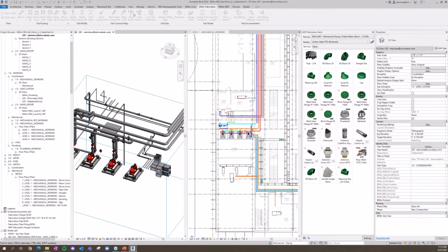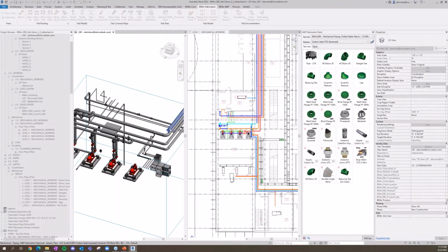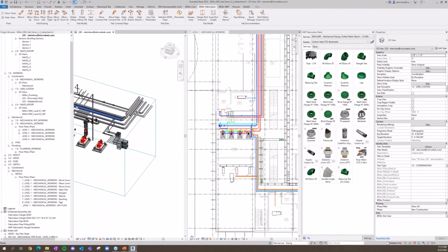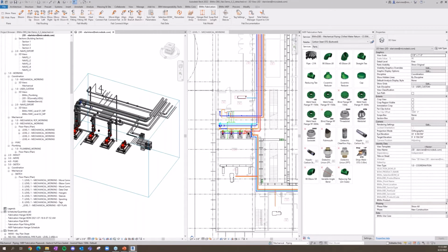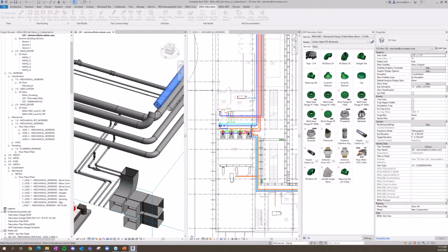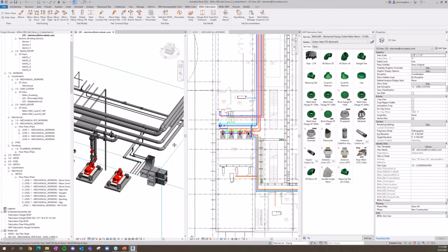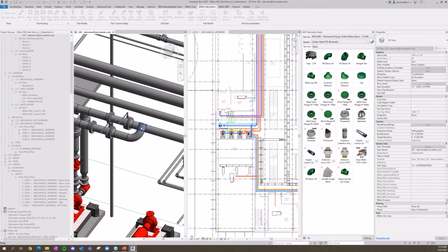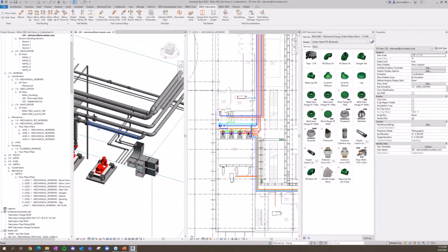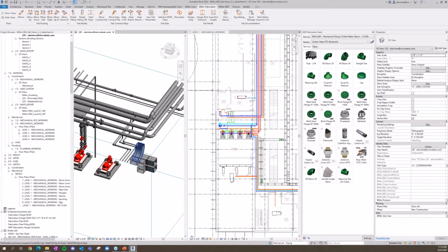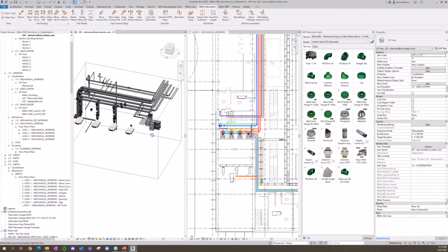Oh, and if I use align branch, we'll make sure to actually click the pipe and not the joint. And there we go. Without moving it up, down, left, or right, it causes an extension of that pipe to move that elbow and extension over to a point where I can use trim to corner to bring those together. You can see that again, align branch, choosing my main, choosing my run, slides it over perfectly, trim to corner, and we're back together. Super, super quick process.